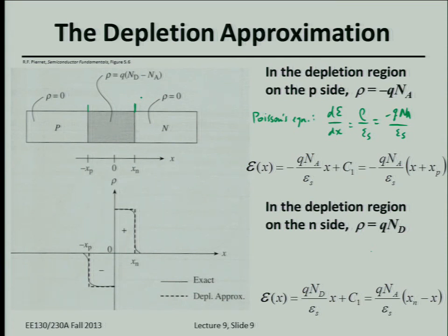Okay, like there's no reason to have electric field in those regions. So we can actually set this equation for electric field to be 0. So this is equal to 0 at, what are we going to do? x equals minus xp. Let's start there first. So the electric field at x equals minus xp is equal to 0. Okay, so that means that C1 is 0.